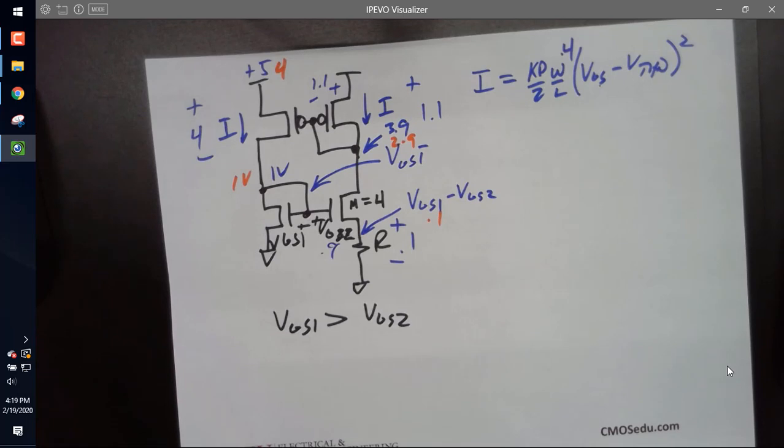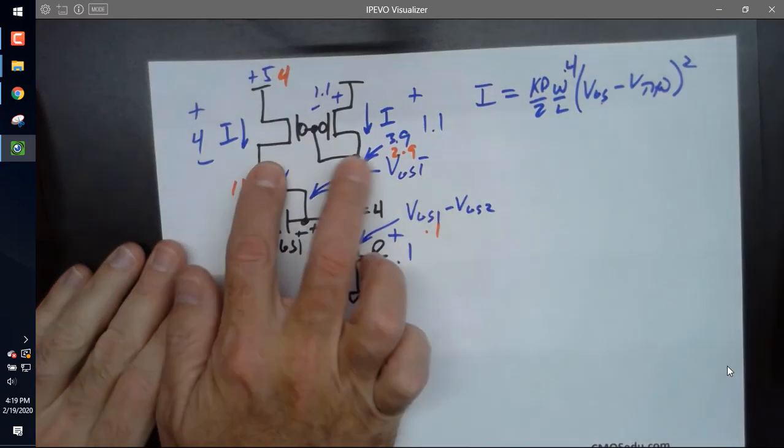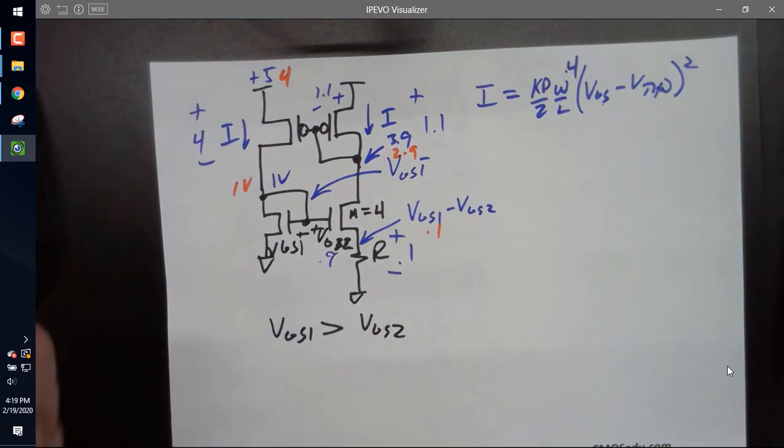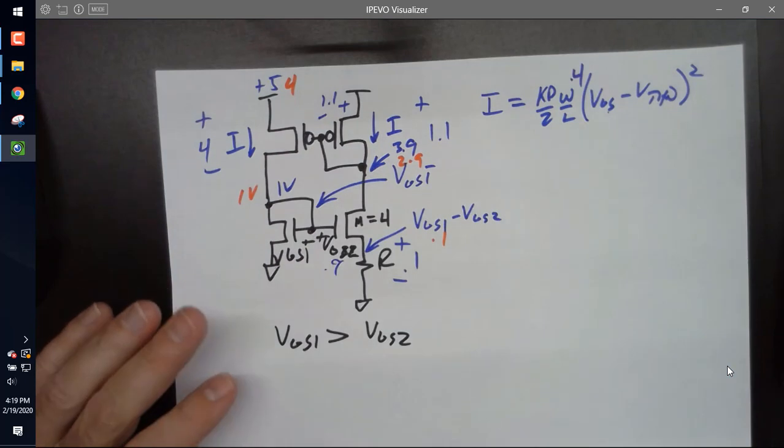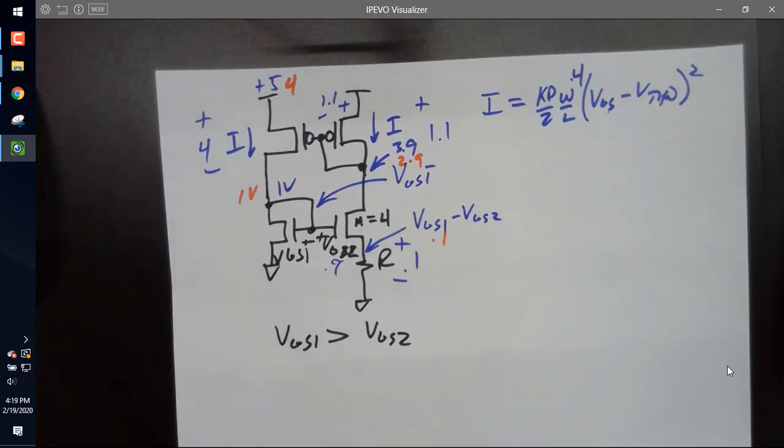So would that change from the drain to source voltage on the 4 transistors in parallel? Is that like, does that have a very minimal effect on the current? Well, it depends on the output resistance, right? If their output resistance was perfectly flat, these wouldn't change, but in reality it's not. So it's not going to be perfect that the current won't change with VDD, but there's tricks that you can do to make it so that it's near perfect. Okay, we'll talk about later.